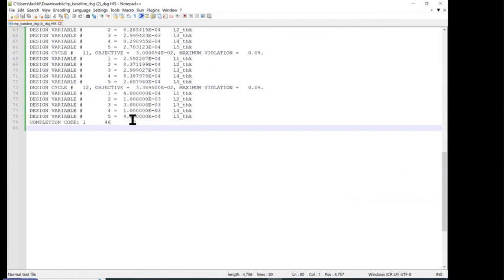So you can see, that tells us how we go about laying that up. Our manufacturing suggestion, therefore, would be 2 plies at -90, 5 plies at -45, 15 plies at 0 degrees, 5 plies at 45, and 2 plies at 90 degrees.